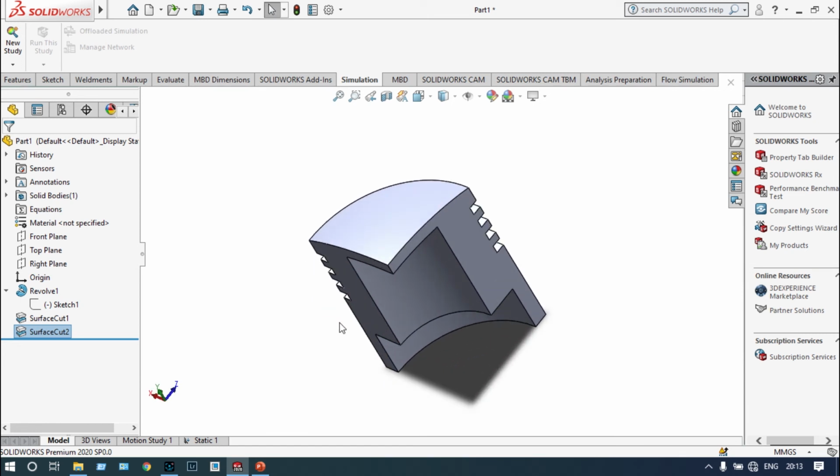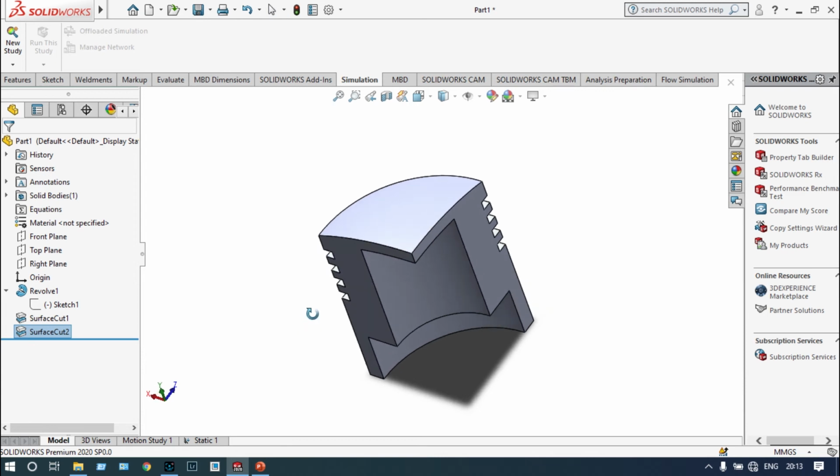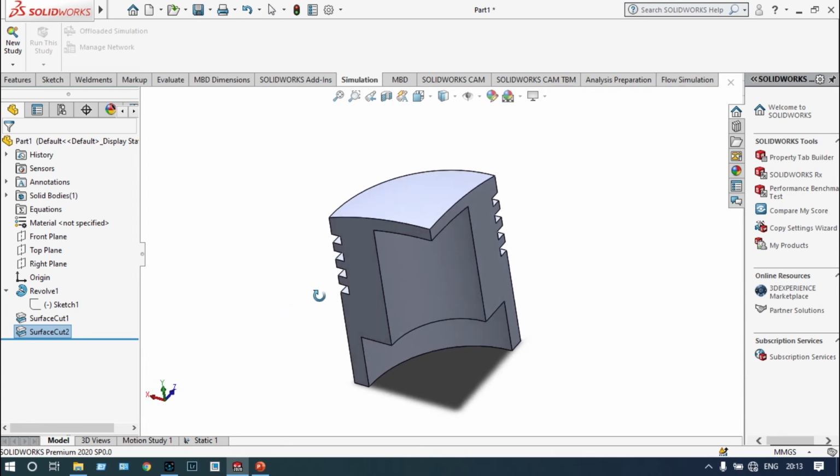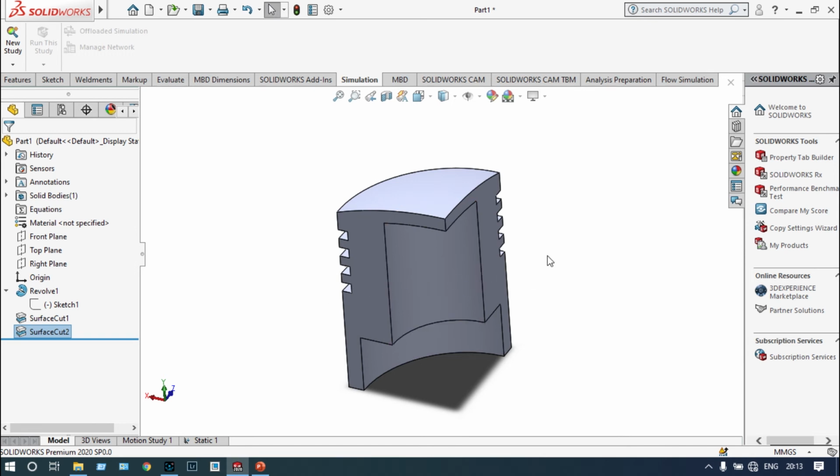Here also we have to apply the same thing, but our boundary conditions will be segmented boundary conditions and see whether the result is okay or not. This is having a lot of advantages because if the model is very complex, and definitely it should be symmetrical, then with segmented model we can have the result within a very short time and also meshing will be perfect. Some cases, it may so happen if the model is very complex we cannot generate perfect meshing.